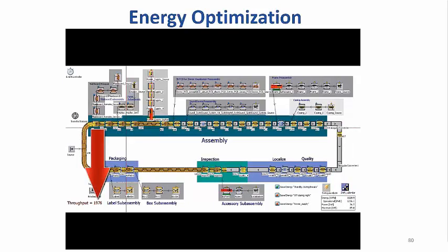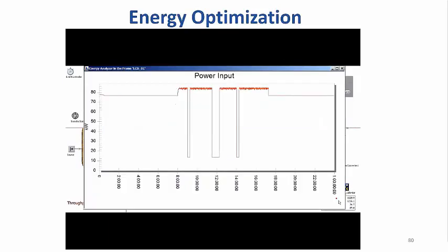Also, we achieved these savings without any decrease in throughput. Let's take another look at the Energy Analyzer Show Plotter option. Instead of being in the operational state consuming about 77 kilowatts during breaks, our equipment is now in standby state instead, consuming only about 14 kilowatts.